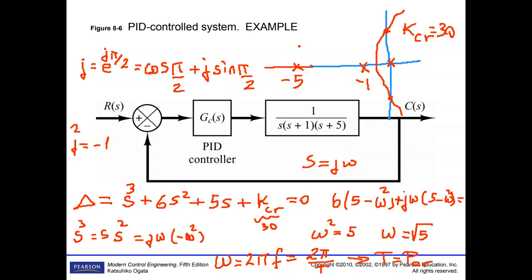Okay, first we're going to define our numerator and denominator, of course. Our denominator, let's say 425. After you define them, for plotting the Bode diagram you just write bode. In the parentheses, you define your numerator and denominator. This is so easy. Easy command. When you hit it, it will give you your Bode diagram.